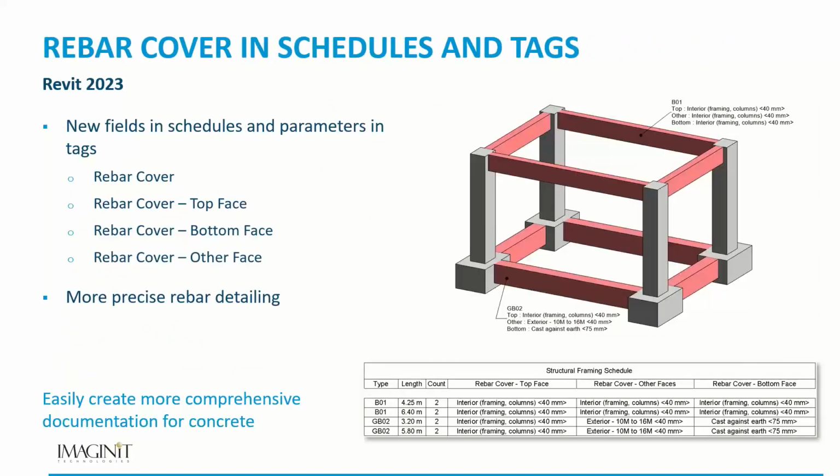Once again, for structural, with the rebar cover, they've added the top face, bottom face, and other face. And this has all been built in for tagging and scheduling as well. So we can create a more comprehensive documentation for the concrete that we're using.